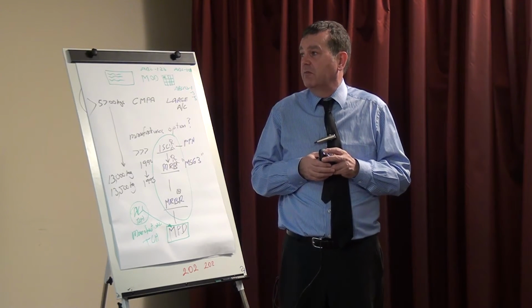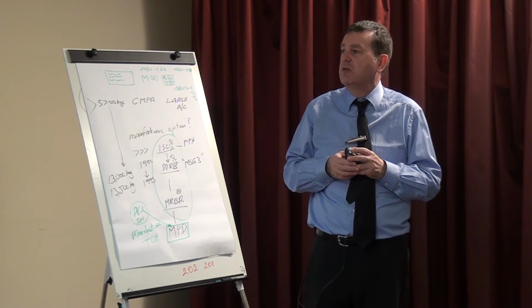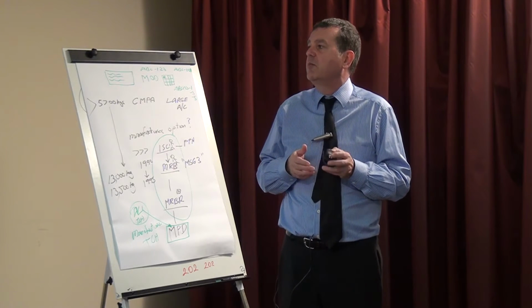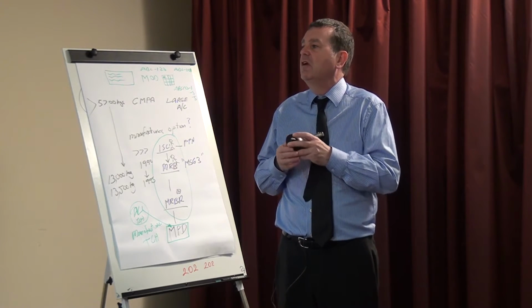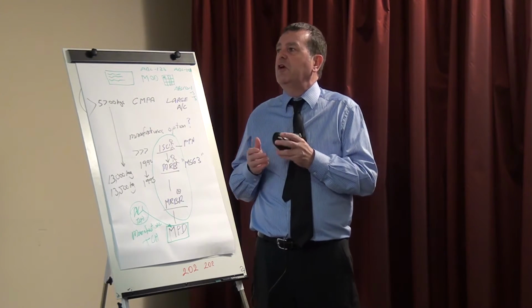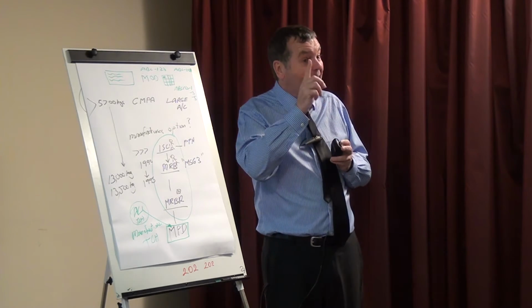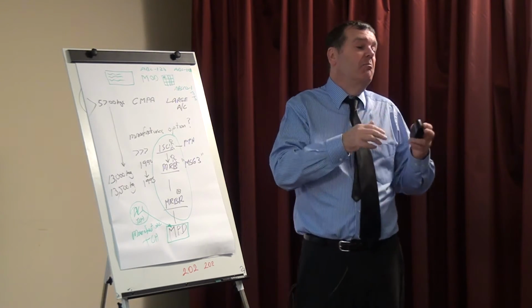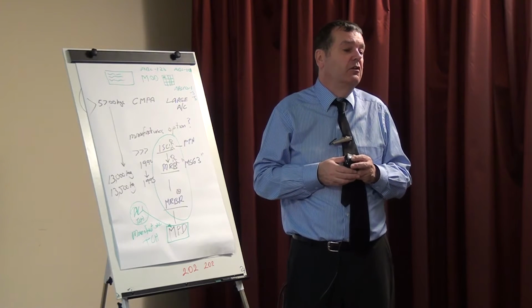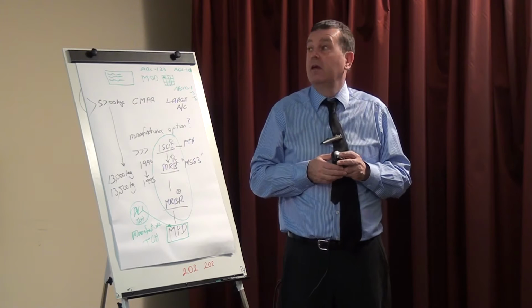On condition, repetitive inspections or tests to determine the condition of units or systems comprising servicing, inspection, testing, calibration and replacement. These first 2 in actual fact was MSG1. Adding to this, which gave us MSG2, was this guy, condition monitoring.